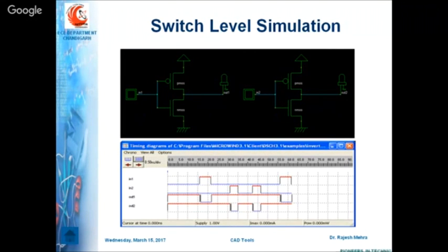So this is one example of an inverter, and here you can see that we have designed this inverter using transistors as switches. The upper part is basically your PMOS, connected with VDD, and the lower part is your NMOS, connected with ground. One LED is connected at the output of this circuit to check the function of your complete design. And we are using one switch as input in order to give 0 and 1 logic to your gate.